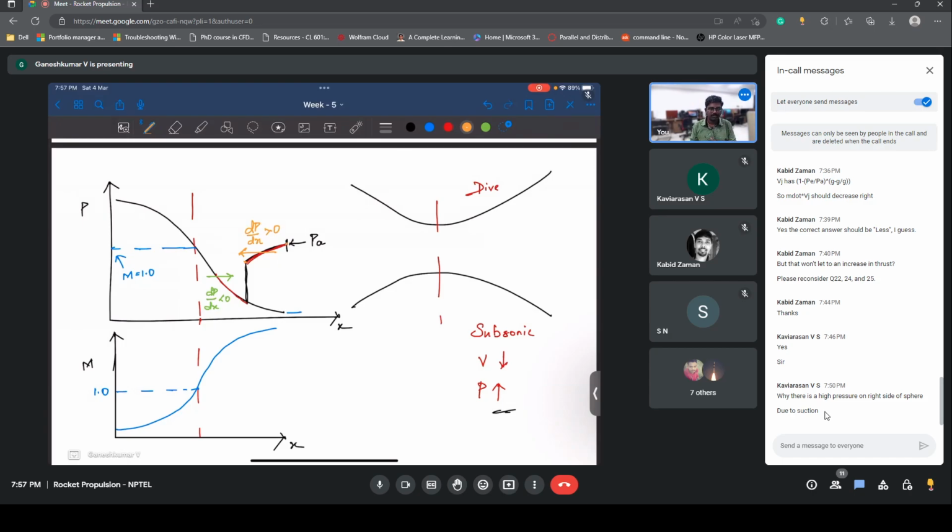So this is the adverse pressure gradient. This is what we call adverse pressure gradient, because it's in the adverse direction of the flow, or in the decreasing direction of x. So this dp/dx accelerates the flow, and this dp/dx will make the flow go in the reverse direction. At some point of time, this dp/dx is overtaken by this dp/dx. So this will be higher and this will be lower.